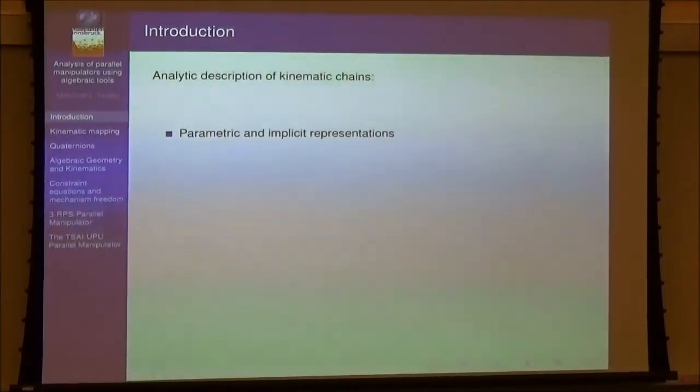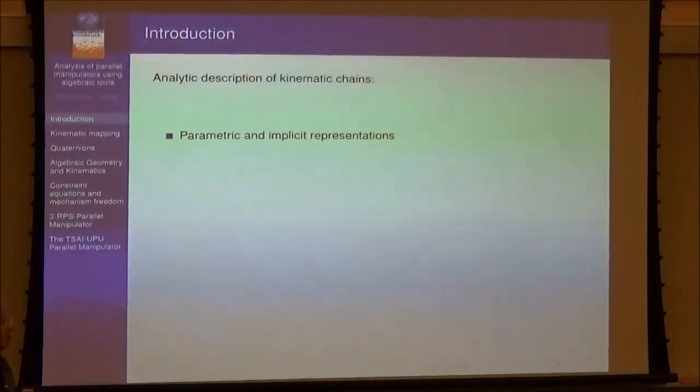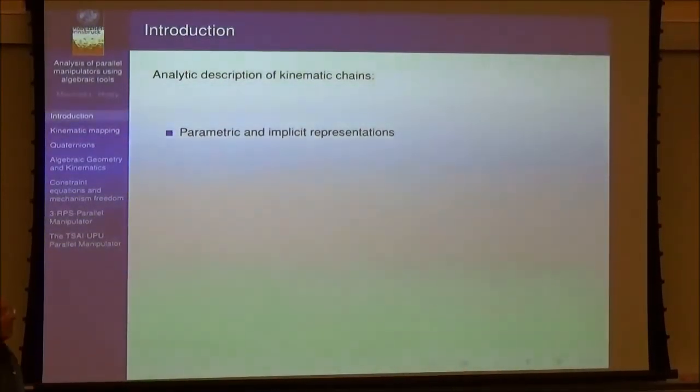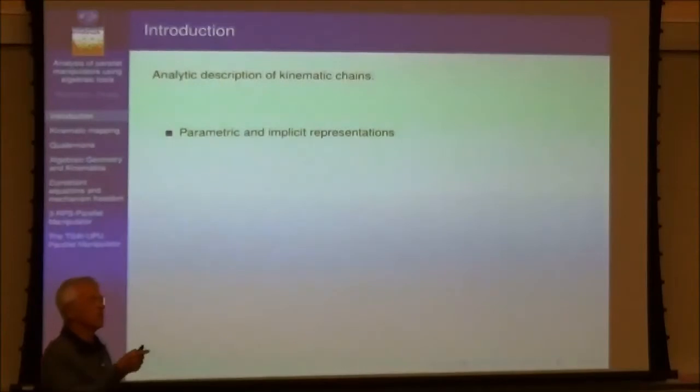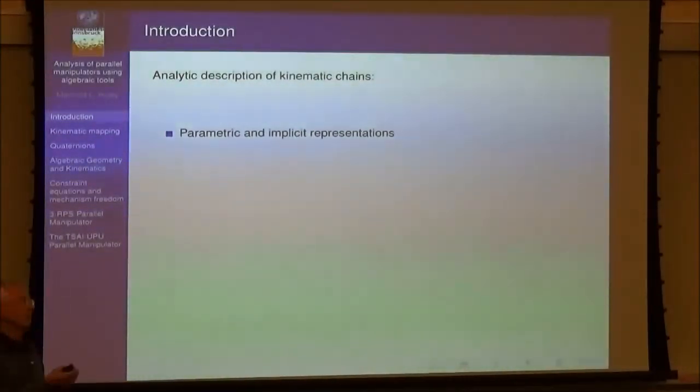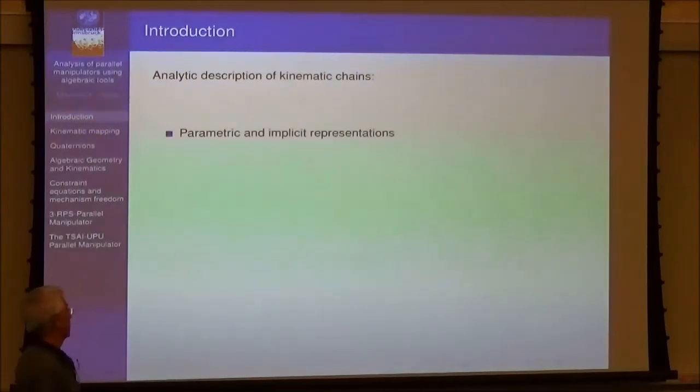The reason is, then we can apply very powerful tools coming from algebraic geometry for the analysis, and maybe you remember the talk of Jeff in the morning, also for the synthesis. The equations you get when you handle implicit equations can be used for both tasks in kinematics, for analysis and for synthesis. You just have to switch between coefficients and unknowns. In the synthesis, the coefficients of the equations become the unknowns, and you are given certain tasks, and the tasks can be positions or poses of the end effector of the manipulator.